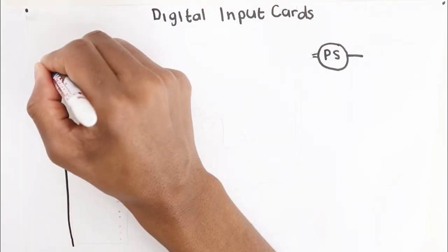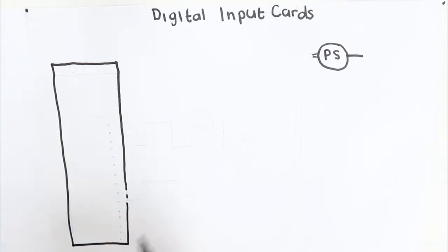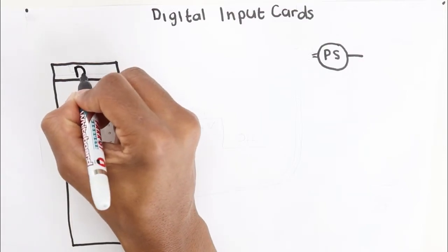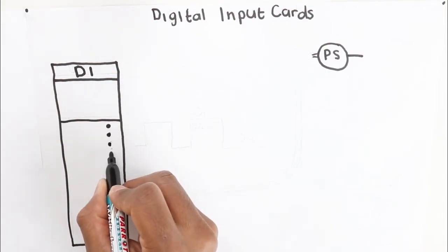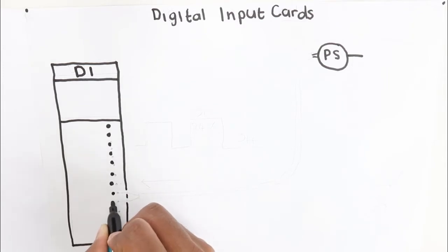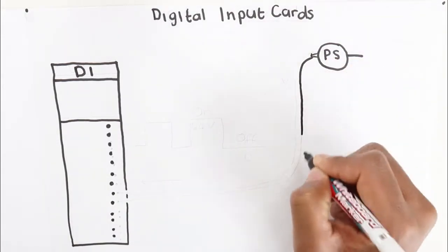to that card. A PLC card is a module that you slot onto your rack that will be used by the PLC to interface with the equipment that you want to be working with the PLC. This could be instruments or devices like motor drives. So we will start by looking at the I/O cards or modules. I'll use the word card and module interchangeably, but I mean the same thing.